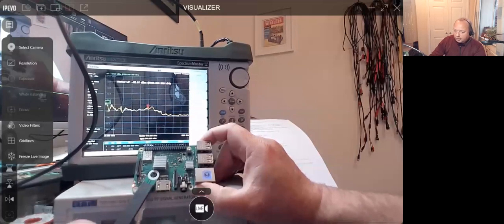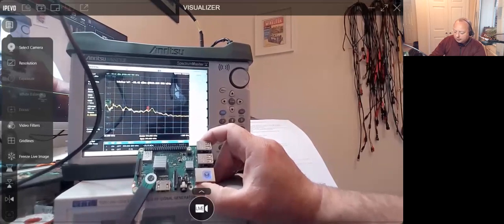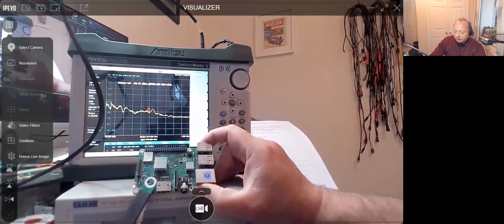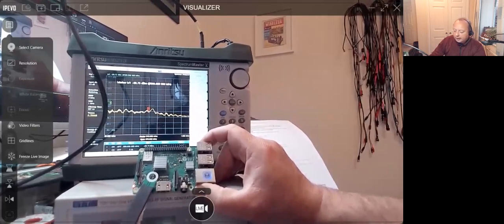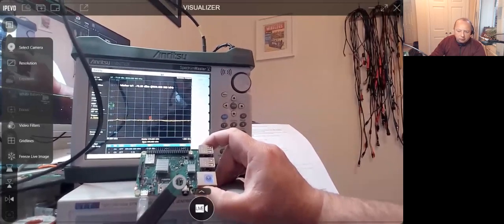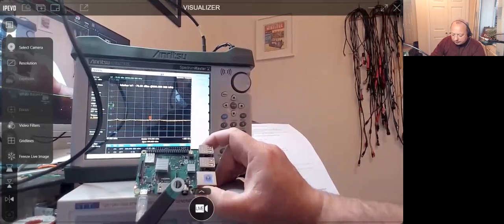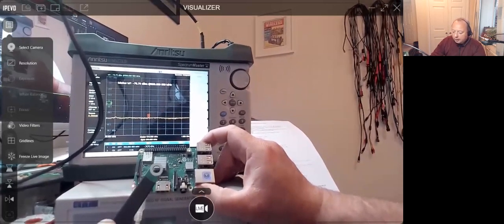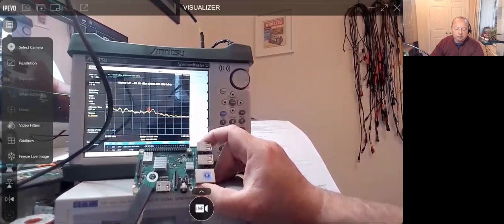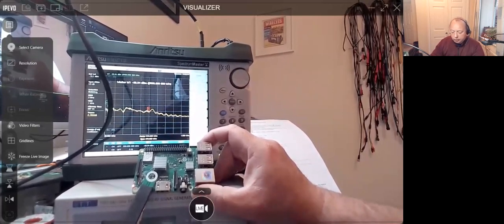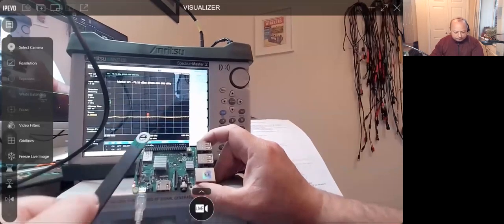Now, of course, it works, and obviously, if you pass EMC, who cares? But of course, as I've discovered in the last week, CE plus CE does not equal CE. You can be very close to the limit, and then completely fail CE because you're adding something else to it, and then you're just the wrong side of the fence.